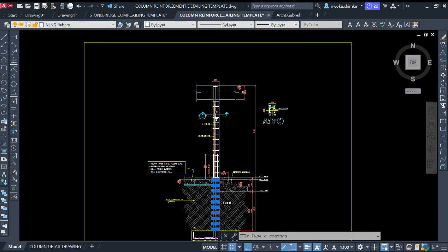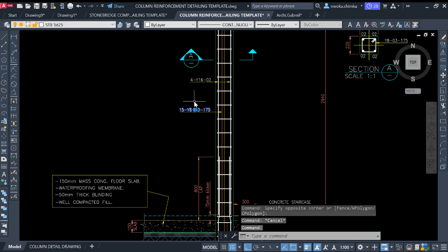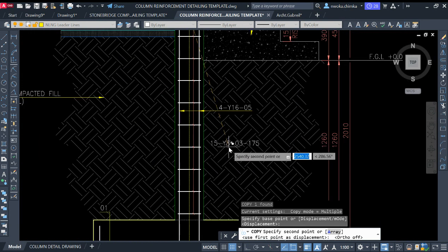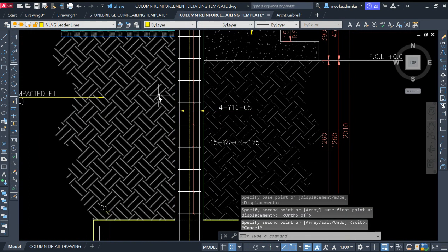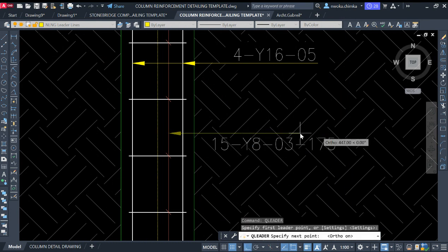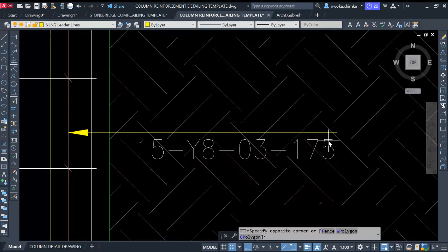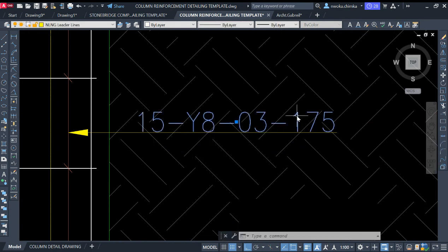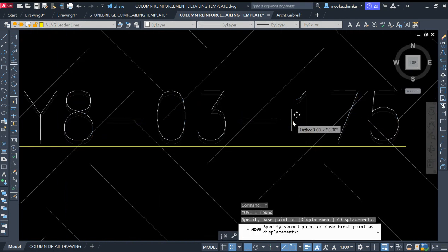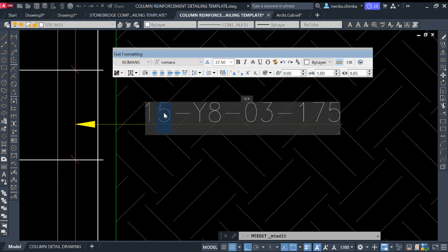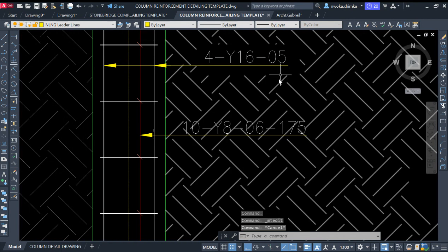So we just go right now and copy this from this point and paste this somewhere here first. Then show our call out line, and then point it out from this point to this point, and then paste it here, directly here. Move this up a bit away from this line and keep it here. And then put this place 10 number of stirrups. And then come here to change the mark to 6 because we have the last one to be 5.